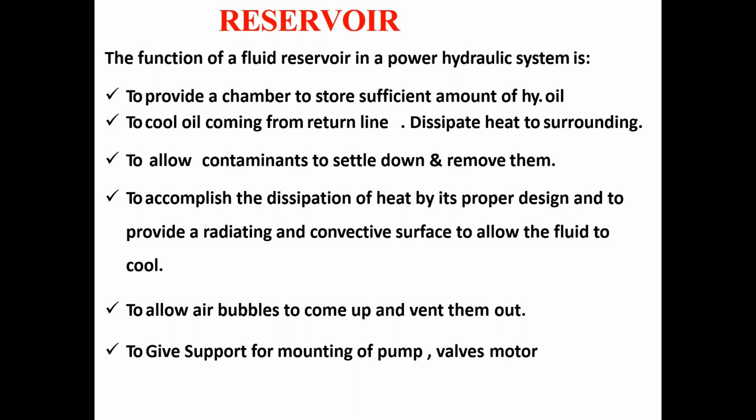So the function of the reservoir can be stated as to allow air bubbles to come up and vent them out. And sometimes if the oil comes up with air bubbles, then this air should be removed in the reservoir. The next is to give support for mounting of the pump and valves motor.